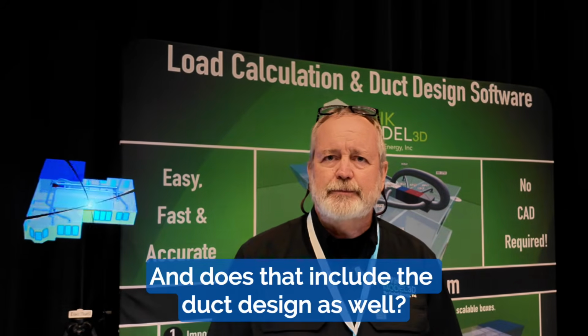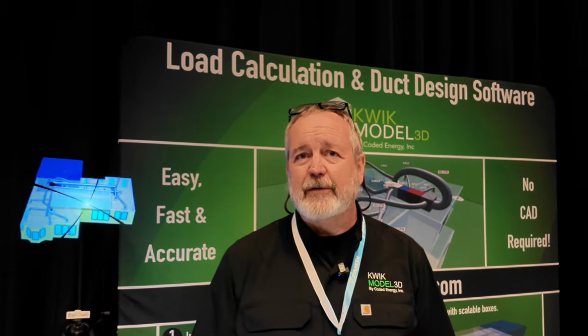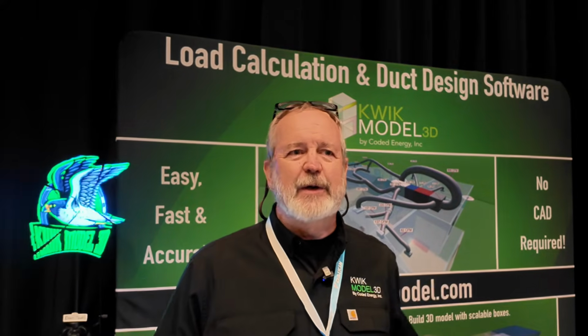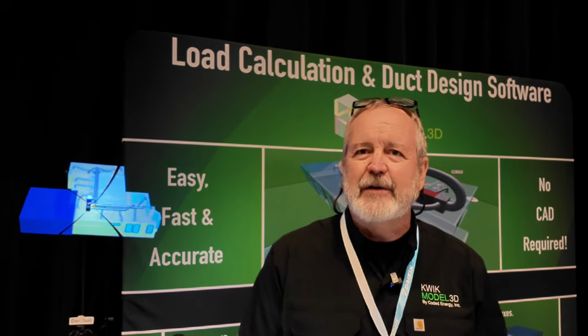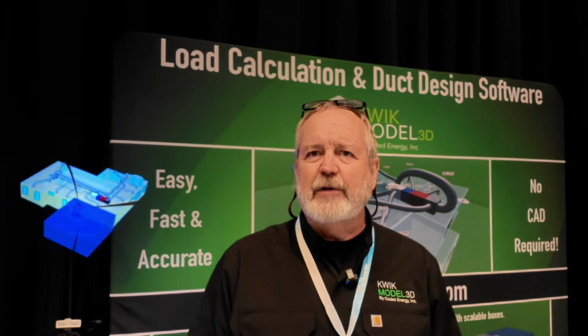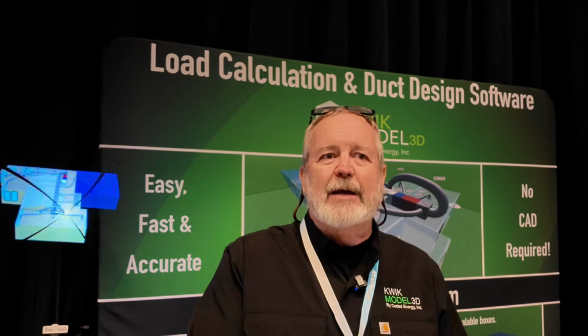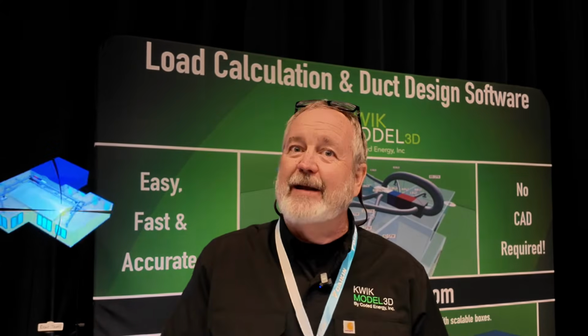And does that include the duct design as well? No, that's just the load calc. The duct design we charge hourly for because we have no idea how long it's going to take, especially in an existing house. Sometimes they're trying to modify the existing ducts or they're starting from scratch. But we provide a consulting service where we'll tell you how big the duct needs to be to each room, and then we leave it up to the installer to figure out how to get it there.